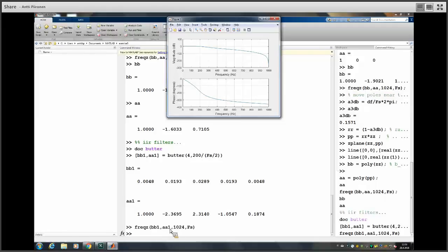And okay, a lot narrower. So here the transition bandwidth is about from 200 Hertz to 550 Hertz. So it's 350 Hertz transition bandwidth. Doubling the amount of poles and zeros, that 350 is now about 35 or 40. So a factor of 10 improvement on transition bandwidth.